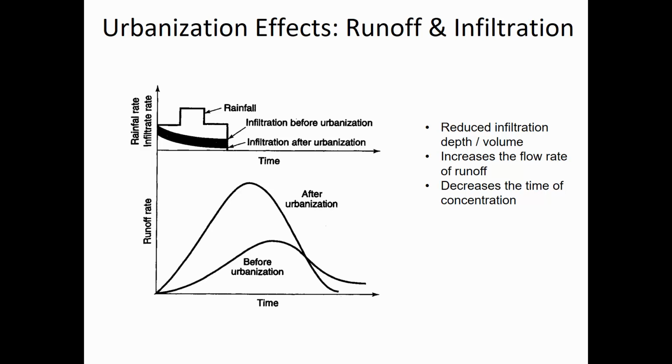And so a gravelly area or a vegetated field in the past would have a relatively low C value, which means a lot of water is infiltrating. But when you urbanize, the march is inevitably to put in roofs, asphalt for roadways, parking lots, and sidewalks or concrete, and none of that infiltrates water efficiently.